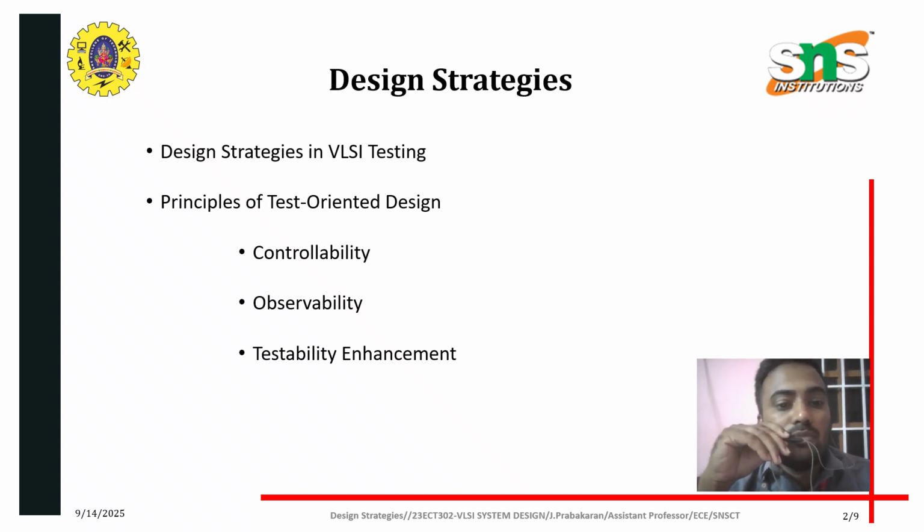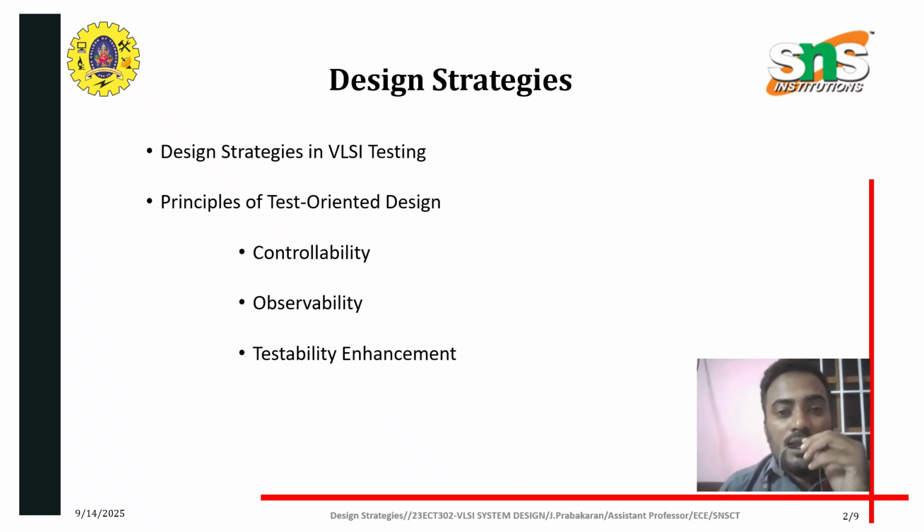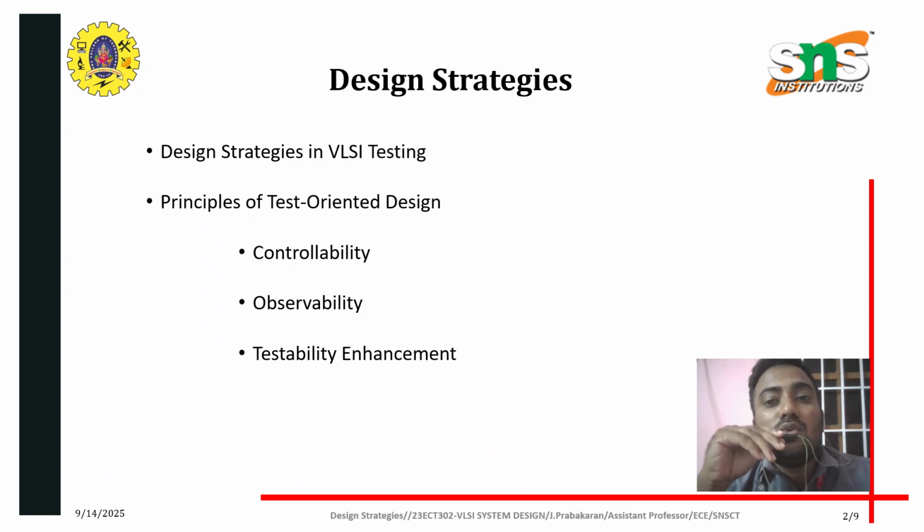This is called observability. And test enhancement. What is meant by test enhancement? Which means adding hardware structure or reusing existing logic to improve controllability and observability.